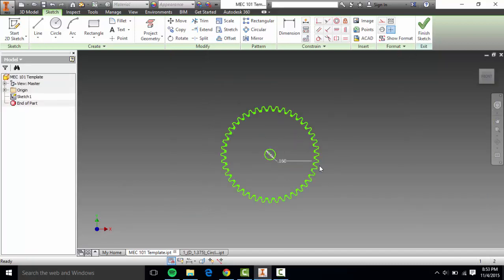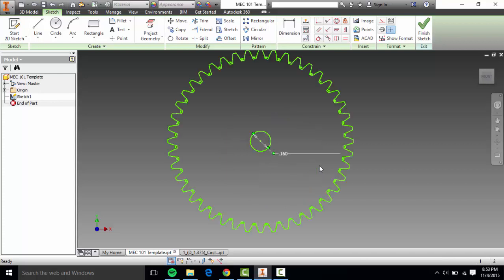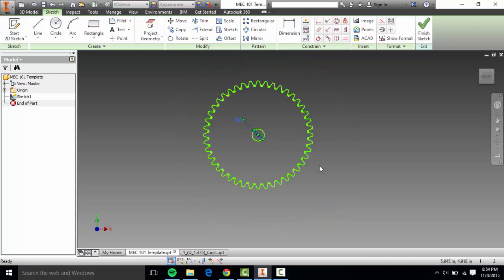Again, I wouldn't change the teeth size. You probably don't want to be changing this 0.16 size if that's the gear you selected, because this 0.16 is perfectly fitted for number 8 screws and the Blue Vex hinges, and it fits the number 6 pretty nicely as well. But if you wanted to do something, you absolutely could.